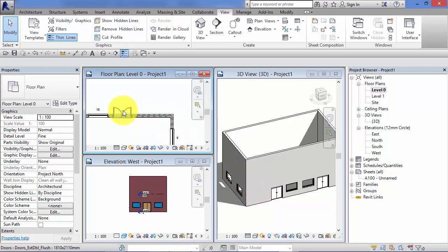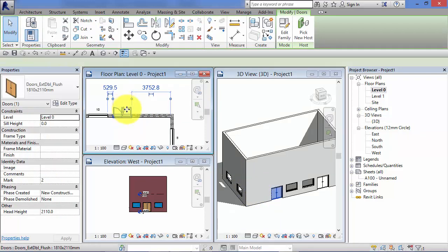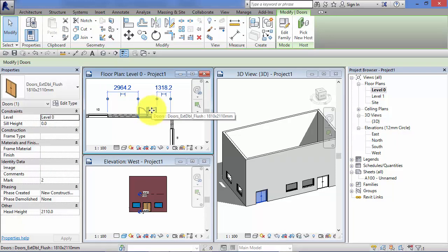Do the same with this door now. If you move this door along, hit the door up and move it and let go. Notice how any view that references the elements that you're editing or moving gets updated in real time. So this feature makes it really efficient to work with multiple views in Revit, so you can start changing, modifying, adding to your design, and you can see the effect of those changes in multiple views virtually instantly.